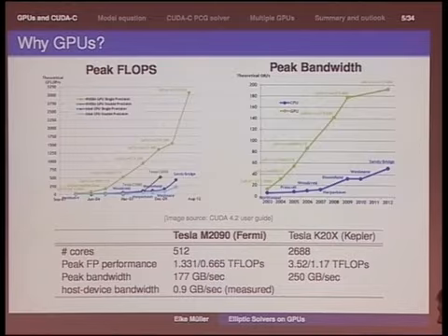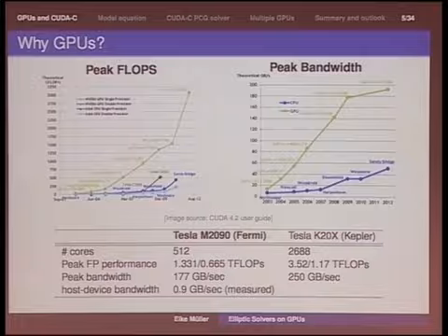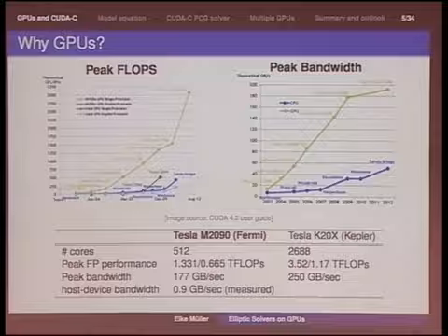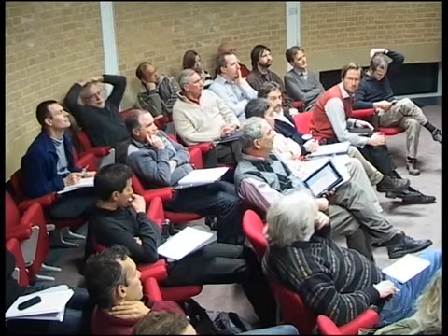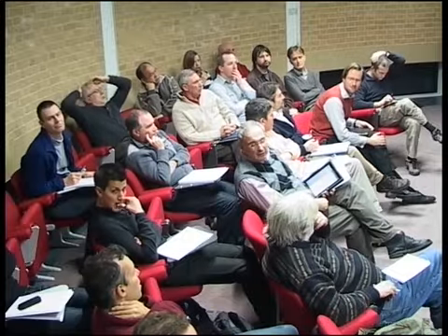That one sounds very low. PCI Express should be capable of more than that, right? That's what I measure. It should, okay, I can double check that. Typically, the quoted number for PCI Express 3 is 16 gigabytes per second. If you're measuring it, you're not going to saturate the peak. It depends what you measure it with. But that's 0.1 of peak, about 10%, which if you were just doing a straight memory copy over a non-busy machine, you'd hope to get a lot more.